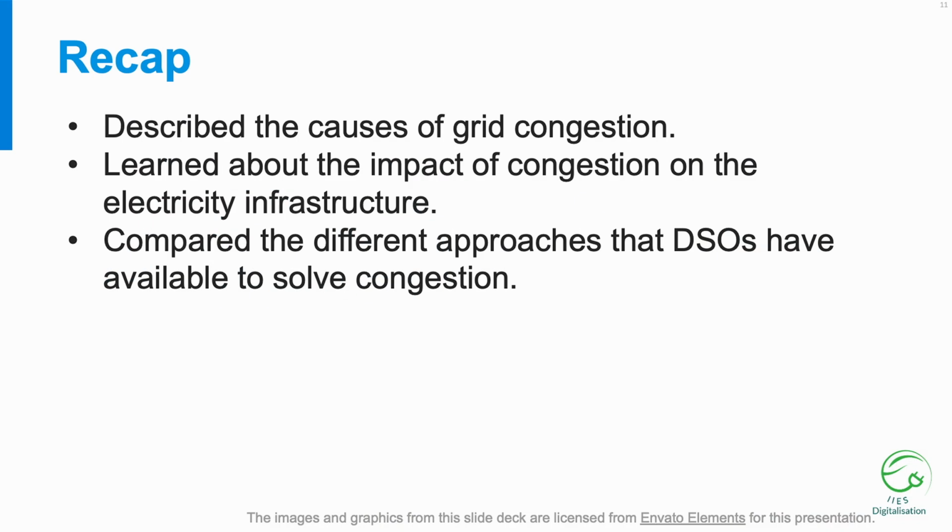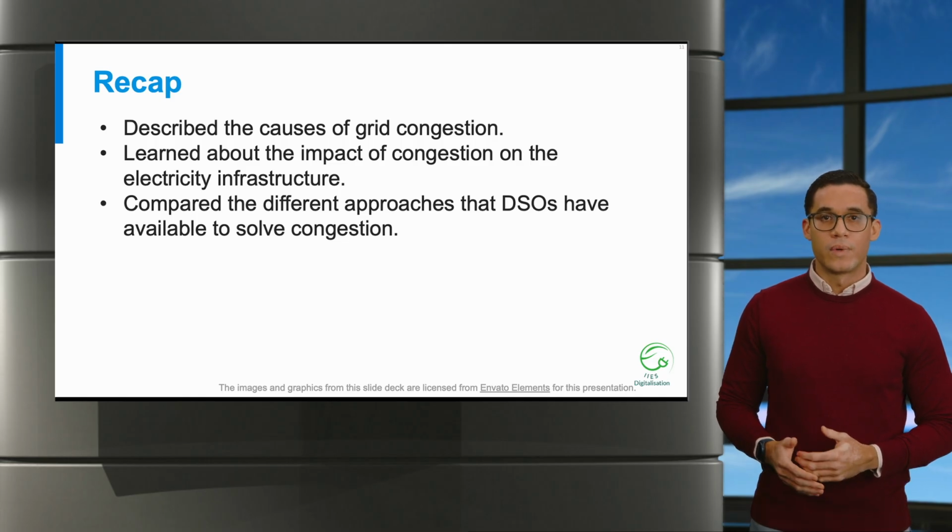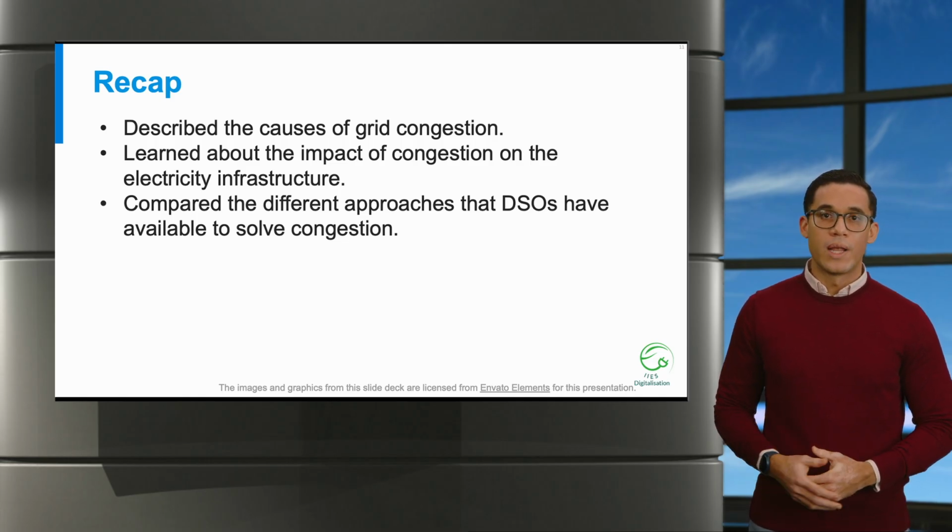In this video, we defined grid congestion as the inability to satisfy current or future transport demand because flows would exceed the grid capacity at peak moments. We also highlighted that congestion is more than a purely technical grid issue. It has an administrative dimension and is shaped by regulation. We then discussed the main drivers: growing distributed generation and electrified demand, capacity lock-in contracts, and regulatory constraints, which can stress assets, reduce reliability margins, delay new connections, and lead to curtailment and higher system costs.